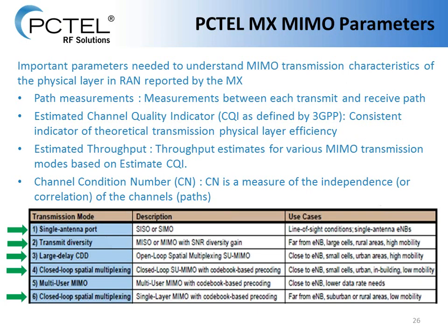What you really want is a very low correlation. This is measured in dB. You want it down around 0 dB. If you have it in the higher range, like 20 dB, that means you have high correlation, and you're not going to get a lot of MIMO gain as a result of that. So what we can do is use the throughput values and then go back and look at CINR and the condition number and find out what the reason for that throughput is based on those values.